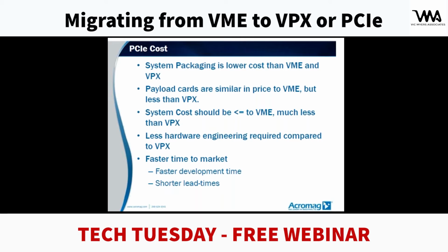Also, there is less hardware engineering required compared to VPX when integrating boards. It's often said that with a PCI Express server, a good software guy could integrate a variety of different PCI Express boards into a system, whereas in VPX, it would become much more difficult for that software guy to do it, and would require a mechanical and an electrical engineer.